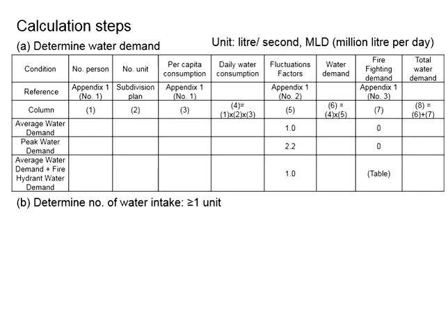I believe you should make realistic assumptions. If it is silent in the guideline, probably realistic assumptions are applicable. You may also consult with the water supply agencies regarding the realistic assumptions. Or you can go for a conservative measure, assuming the fire hydrants are being used concurrently for one full day. But this is going to significantly add to the total water demand. If you have an idea how to compute this, kindly share your experience and thoughts. With that, you can calculate the total water demand under 3 different scenarios.